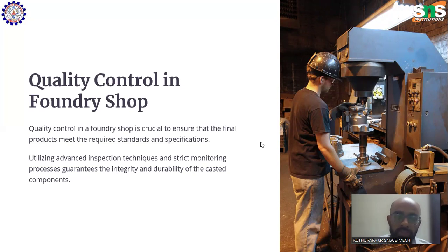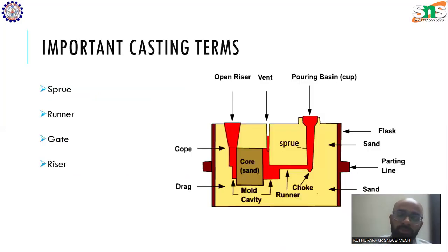as you can see in this image, we are using different vents for providing an air gap as well as for pouring molten metal into the sand casting. What happens is that after solidification, the metal tends to remain around these holes. So there will be a runner and riser attached to the finished casting. So you have to remove those excess projections from the sand casting to make it usable. That process is called fettling. Once the fettling is done, then the secondary machining process can be done.